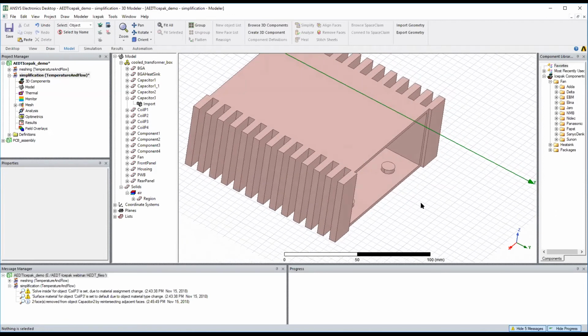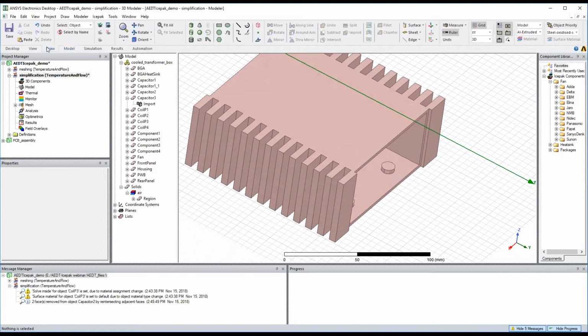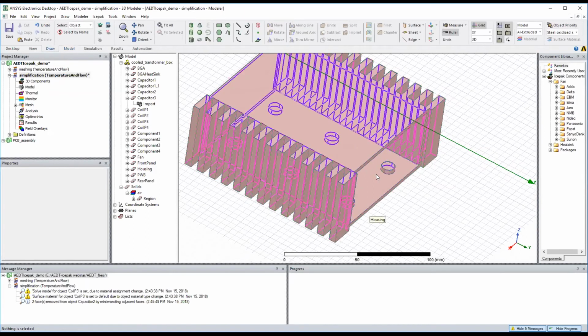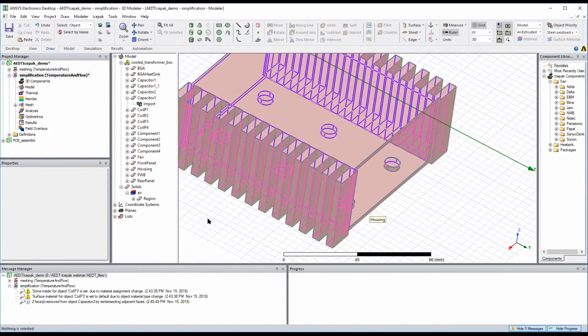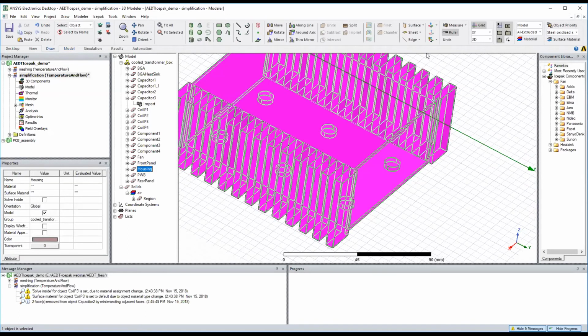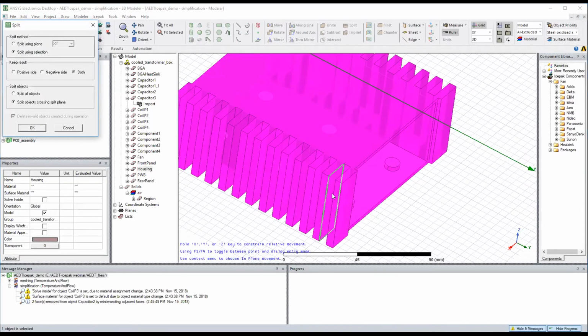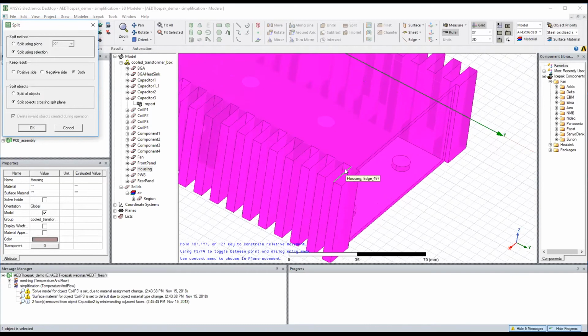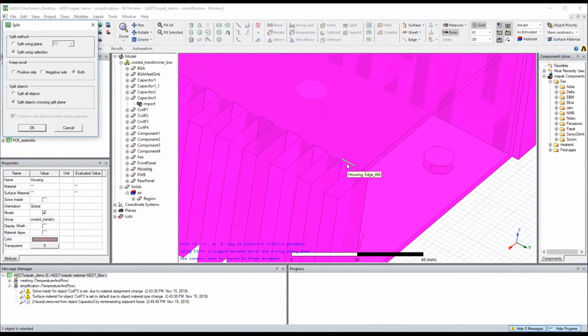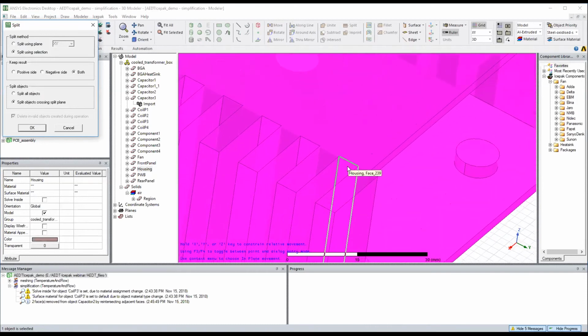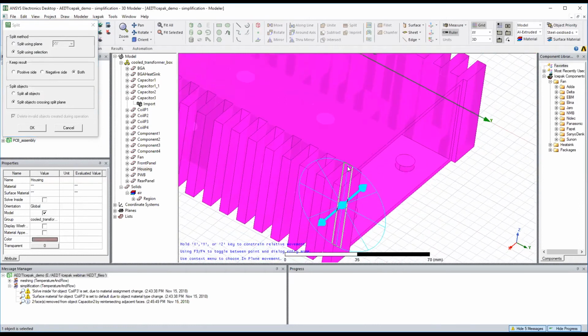split off objects. So again, what I'd want to do, and this is actually in the draw menu. So if I select the housing and then I go to split, and then all I have to do is pick the face that I want to split it on. There's some options here in the window that showed up in the upper left-hand corner.